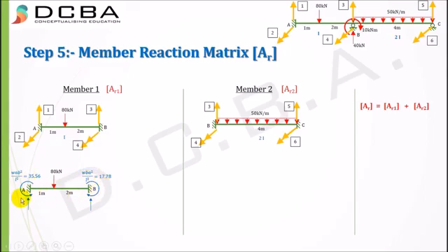I hope you know about the fixed end moments by now, because that is the prerequisite for everything. And the reactions can be found by simple equilibrium conditions. If you take the summation of moment at A equal to 0, then you can find this particular reaction, and then from summation Fy equal to 0 you can find this reaction.